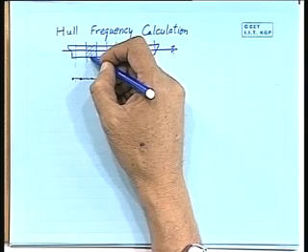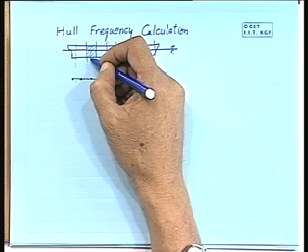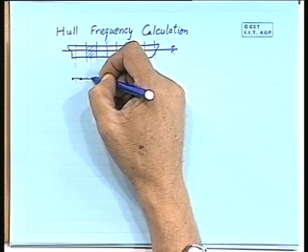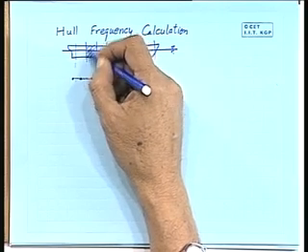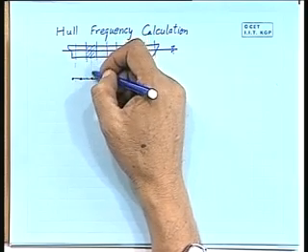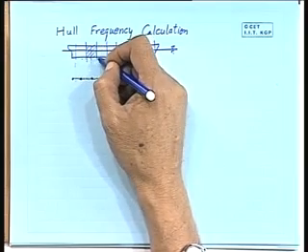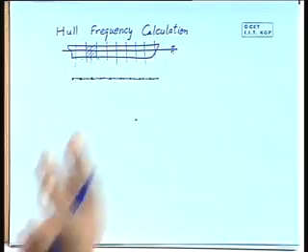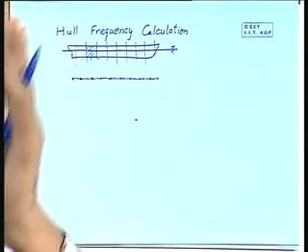So, I can find out the added mass coefficient of this particular section. The added mass is added to this complete thing on the basis of this added mass coefficient spread over this distance. So, the mass of the ship plus the added mass of the ship, these two together move